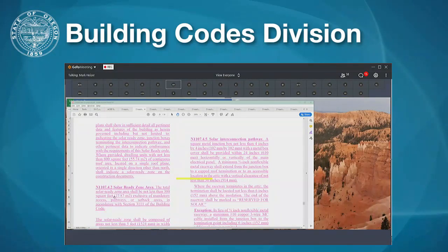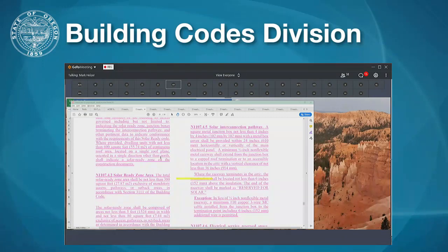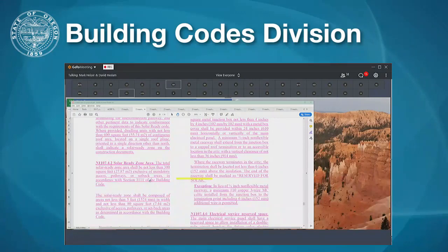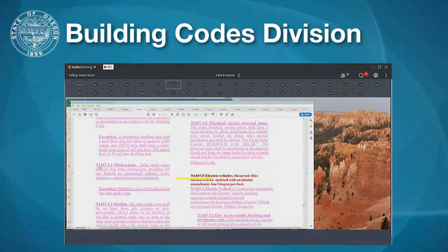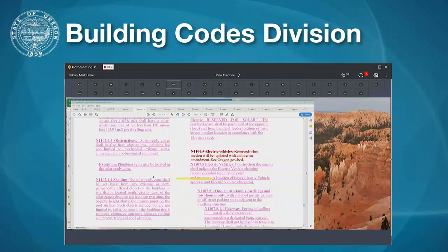And if you're, it shall not be less than 300 square feet. The reason we're looking to break this out separately is that some homes may be small enough to be outside of this. If they don't have this, they aren't completely excluded from doing the REACH code. So this is a solar ready path in the REACH code. Right. And that's why we're discussing this now, because some homes are shaded from obstructions that we'll find down here in section N1107.4.3 or shaded.